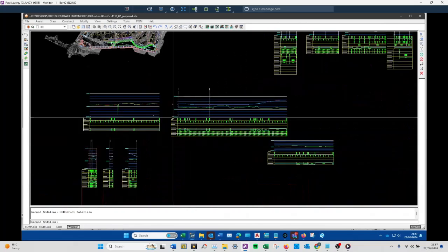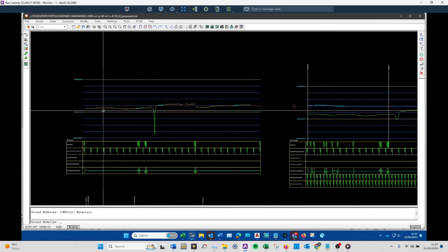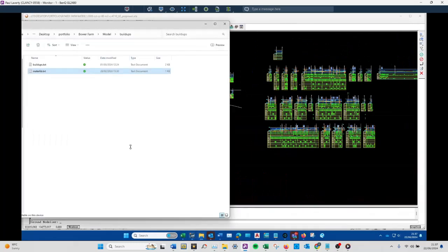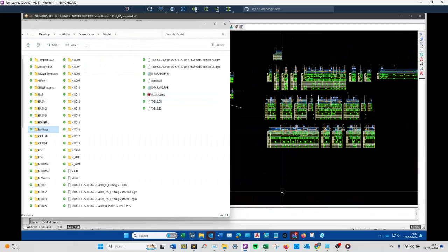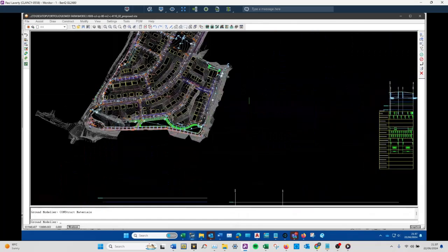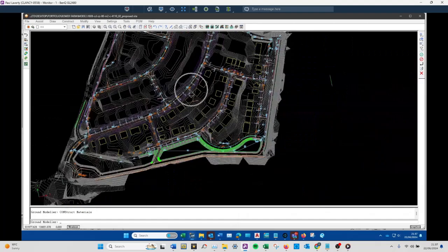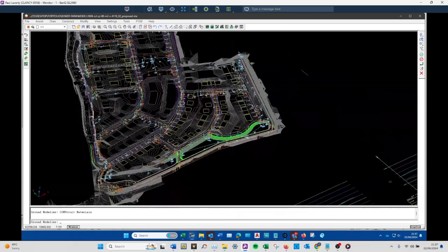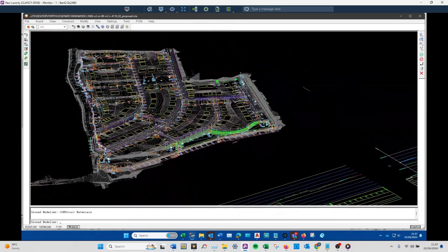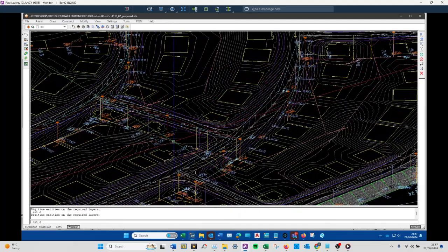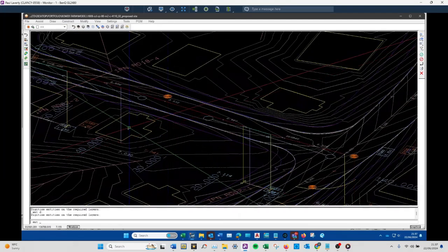But the main thing is that you always have this folder called buildups, and that's where you edit your materials and your construction depths for your different paving areas. You could rename it, you could move it to a different location, but if you do, PDS will automatically create a folder called buildups in this location because that's where it always drops it. So there is no point to move it, there is no point to change the name, just leave it as is.